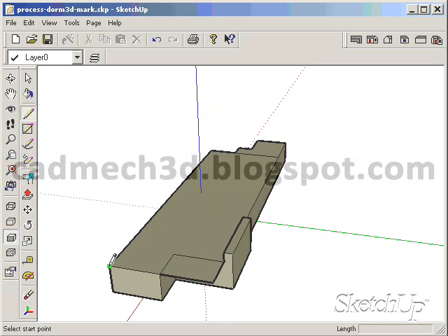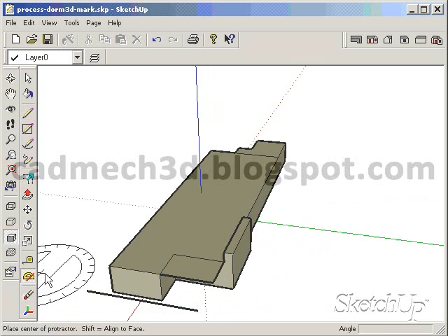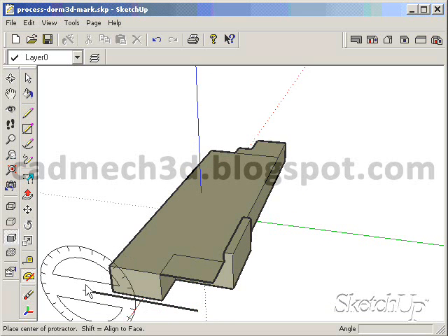Now I'll draw in the width of the roof by inferring out in space from each end of the undersoffit. This gives me a single edge indicating the full width of the roof. Now, by locking the protractor to the narrow end of the house using Shift, I can place a construction line at a roof slope of 6/12 coming off the edge we just drew.